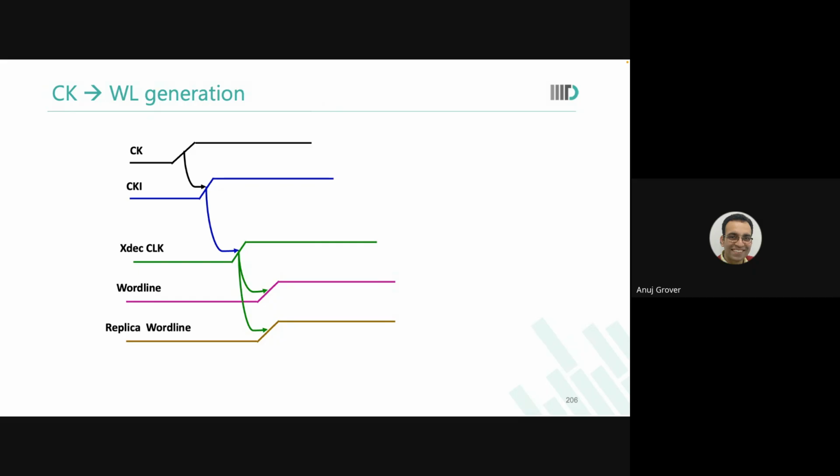Then the bitline also I put at the far end, and I said, okay, the entire bitline delay will be tracked. And then I brought them in like this. So what does this ensure? That the cornermost sense amplifier has the minimum requirement of the offset, but the sense amplifier right next to the control region would get a lot of differential at its inputs. Do you realize this?